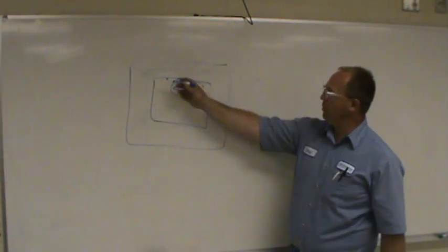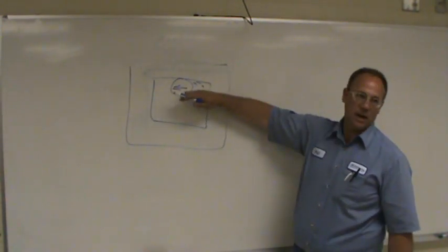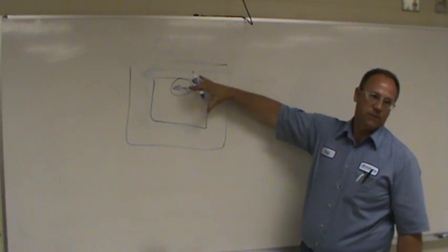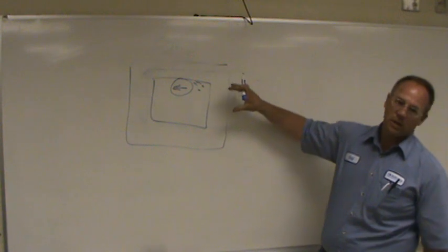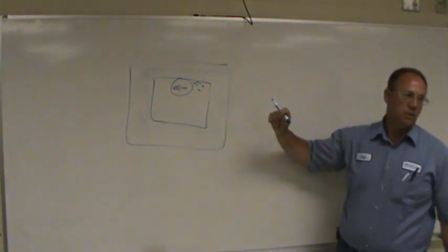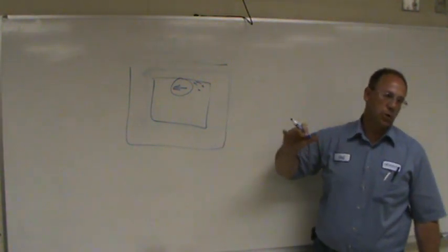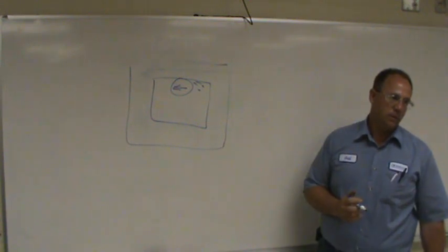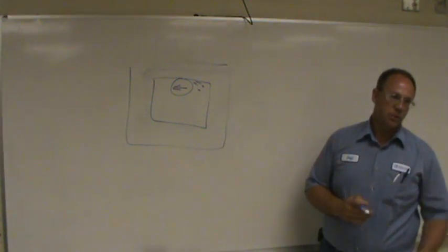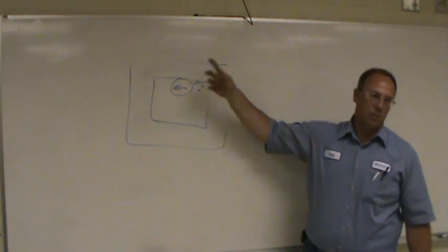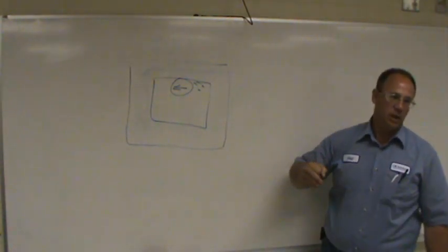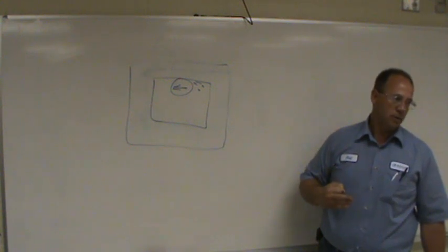I want it cutting that way, still to the left side of the line, so it's a G41. So basically in a CNC situation, you always want to climb mill, and by rule you're always going to use a G41. It's up to you as a programmer to decide which way around that part you want to go. So I'm climb milling and using the G41.